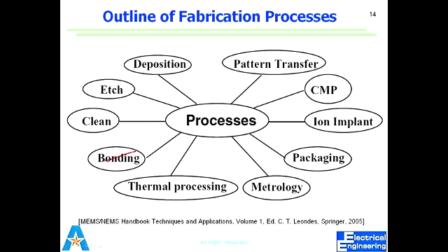How do we do that? We coat this wafer with a thin layer of a material called photoresist. It's a liquid material. We coat the surface, we heat up the wafer, and the liquid solidifies. So now we have this thin layer of material called photoresist. Why do we call it photoresist? Because if we expose it to a certain wavelength of light, it undergoes chemical changes, which make it soluble at those parts or insoluble, depending on the type.